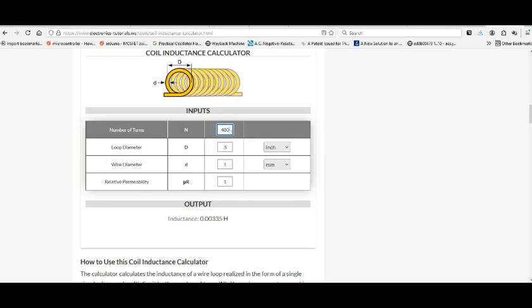0.5 and 4,000. And this all stems from when we looked at all of those formulas, it was always R squared, N squared, the number of turns squared, that was affecting inductance. So that's why, even though it's not good that the diameter is getting smaller, it's more than compensated for, with the given length of wire, by adding more turns.